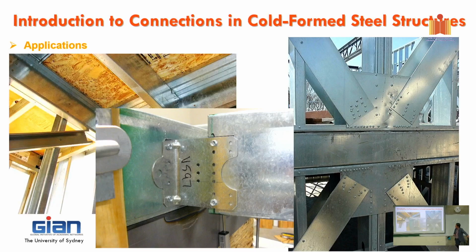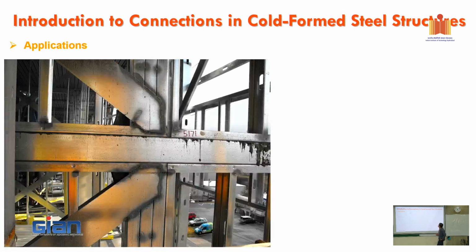Right, that's a typical screw connection, and that is a problem I told you about before, right? Because of the flange, they have to have a bit of spacing between the end of this beam and the web of the other beam.